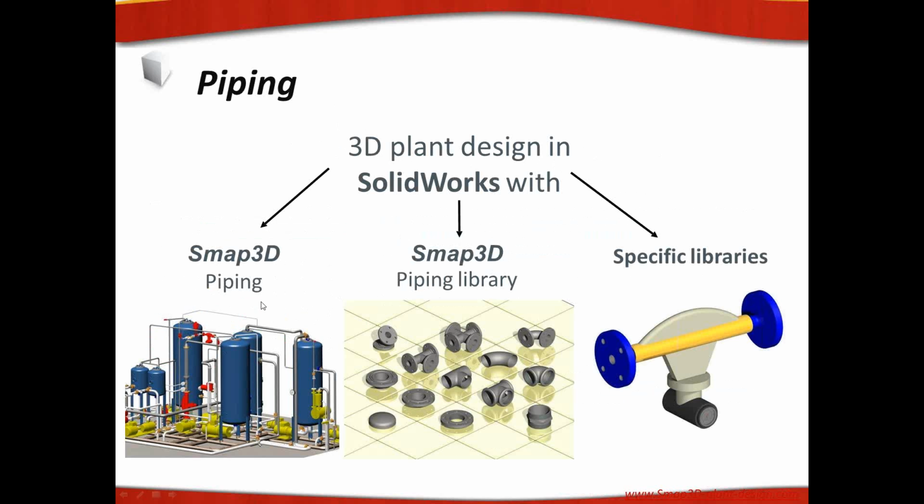The piping solution, as I said before, is primarily within the 3D modeling in SolidWorks, and it uses these quote-unquote template parts. They have a standard parts library that goes along with the components from P&ID and the like. And you can see here where you can basically mate them, integrating them into a 3D design. For the most part, it's a drag and drop solution, but it does require quite a bit of 3D sketching as well to define and design the piping itself. And then you drop in your components, your elbows, your connections, and so on. So it's a really nice, quick, and simple solution.